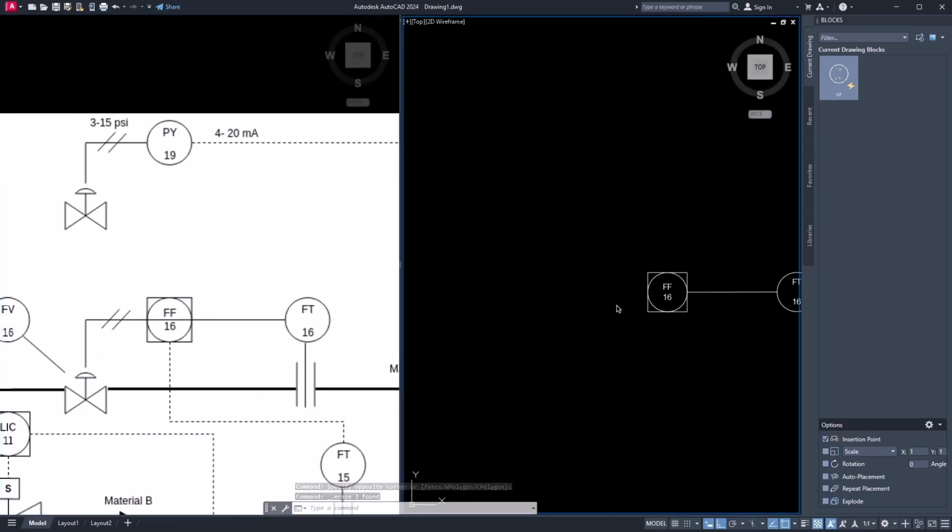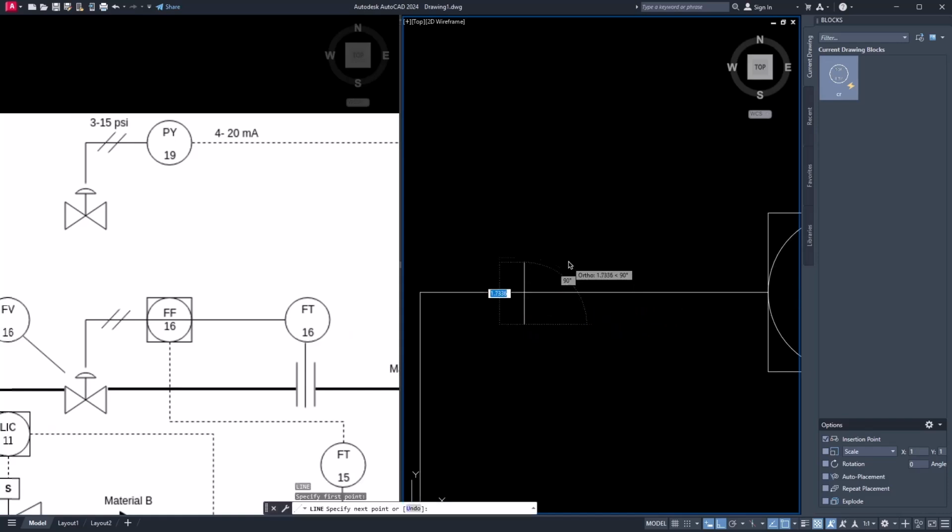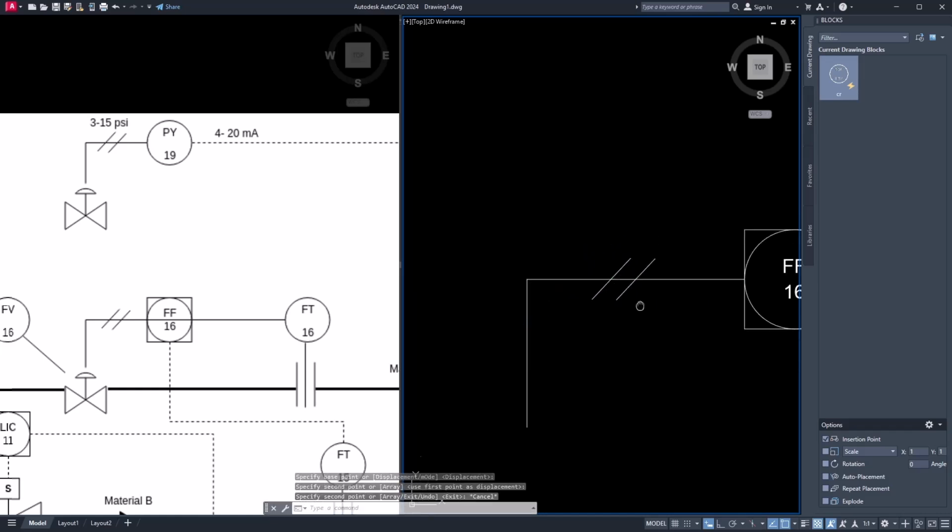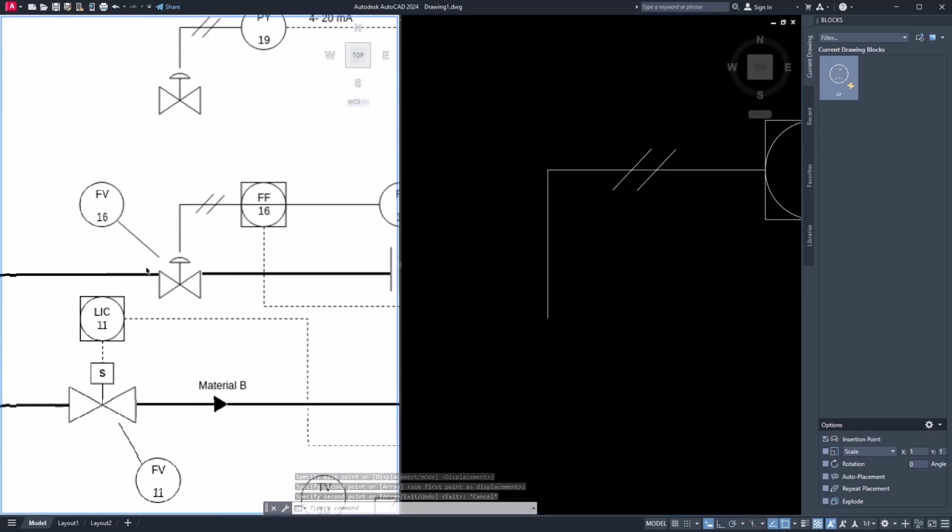Now I can draw a line. Click it, click down. Two lines are here. Now maybe turn off ortho. Excuse me, just wait. Turn off ortho, then I'm going to draw the line. Now hit tab and type the angle 45. Now all you want to do here is copy this from the first point to the second point. Now we have the second block, which comprises 2 triangles.